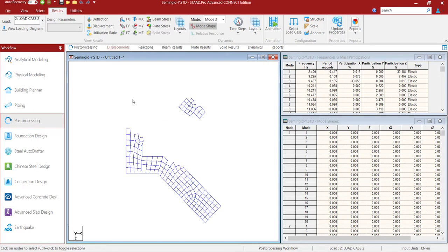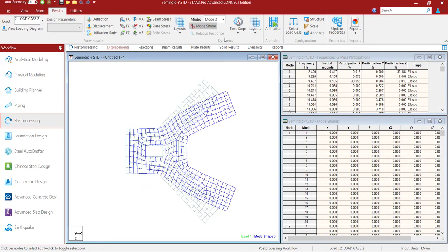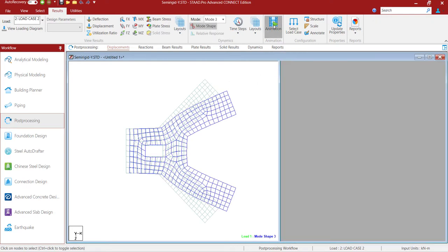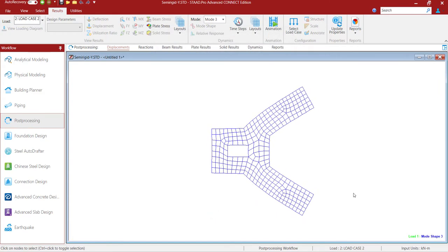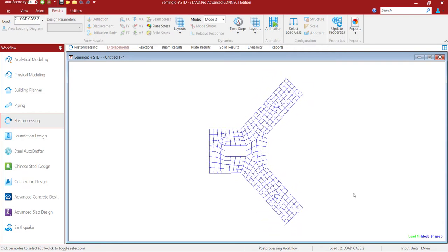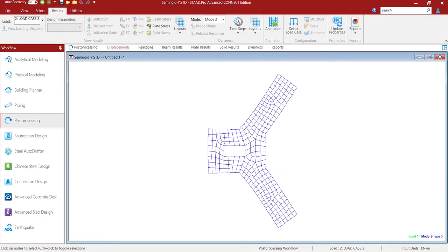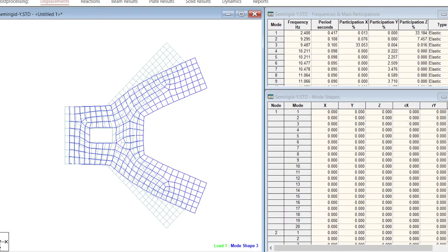Now here too, you can see that these two wings are also trying to behave like a semi-rigid diaphragm because you can see they are trying to undergo some internal, in-plane deformation. If you also take the mode participation factor for this one, here you can see the shape of these two opposite wings. You can see it's an open and close mode, because the two wings are trying to come close to each other and then again recede from each other.